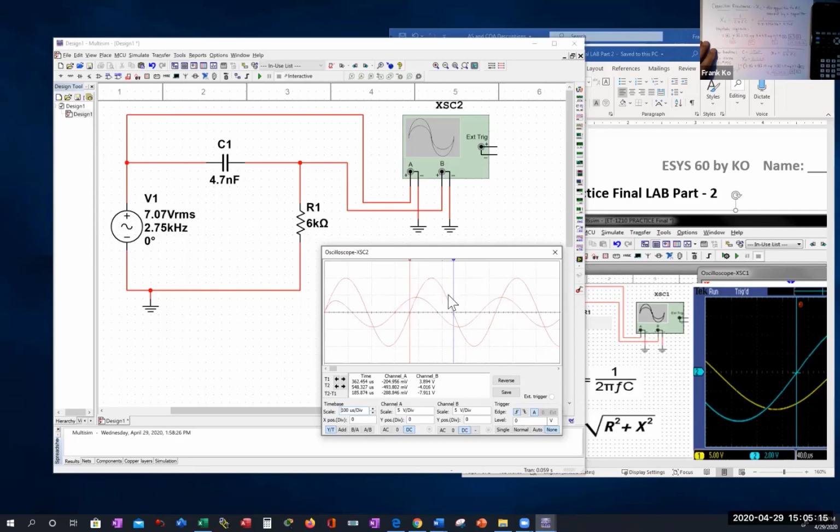This is where the positive swings over to the negative, and I can move this one over to here. The intersection point is where the positive of the smaller waveform switches from positive half cycle to negative half cycle. That is my 0 point. And if I look at the time distance between these two, am I still somewhere around 68 and change microseconds? Okay, so that information will be very important for us in a little bit, because we're going to do the math to do the calculations and see if all of this matches our calculations.